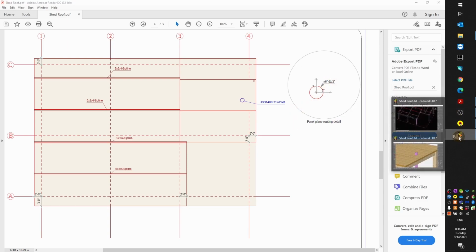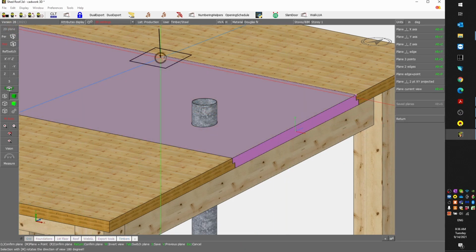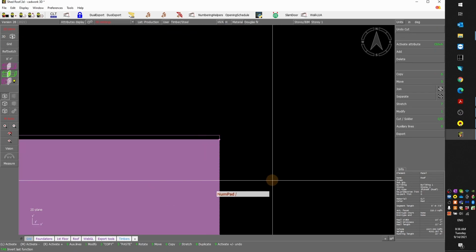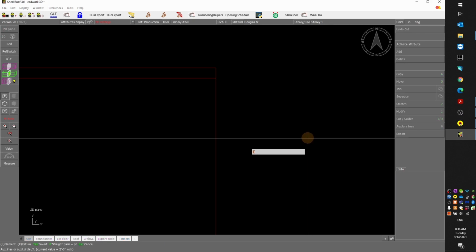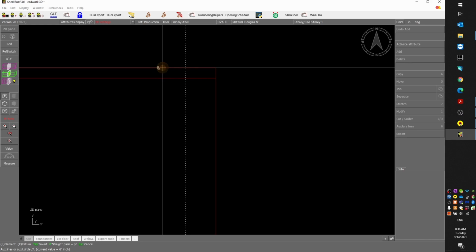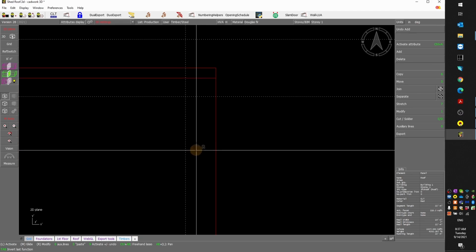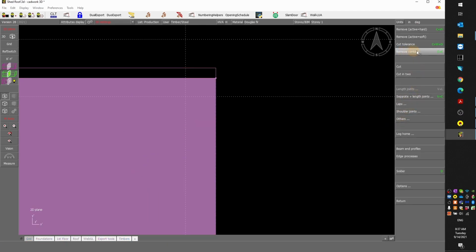So let's do this. I select the top of the panel, right click, it jumps in, then I hide the rest, and let's do an offset E 6 inches, 6. So from the end, from the top, oops, slightly underneath, and then I can select the panel, cut, remove contour.